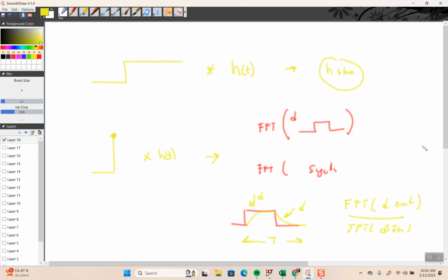The reason why I do the derivative is that it can be very hard to get an impulse response, to set that up properly. But you can do a step response. And the derivative of the step response is the impulse response. And then because it's repeating, you can just take the FFT, take the two ratios, and you will get it. It's buried in there somewhere.